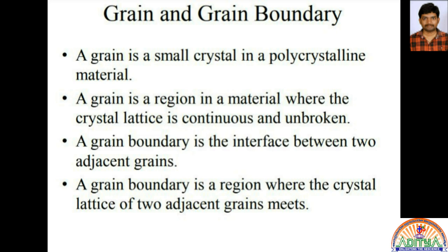Okay, so this is nothing but a grain. And coming to the next important thing here is a grain boundary. So grain boundary is nothing but the interface between two adjacent grains. A grain boundary is a region where the crystal lattice of two adjacent grains meets. So these grain boundaries have a specific structure, energy and mobility. So these are the characteristics regarding the grain boundary.